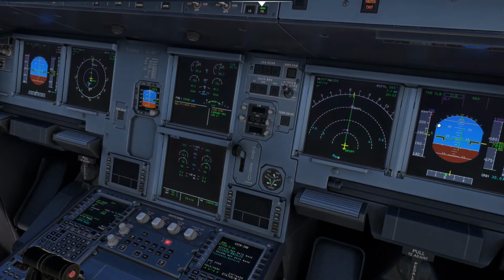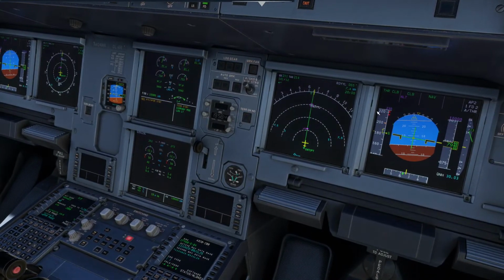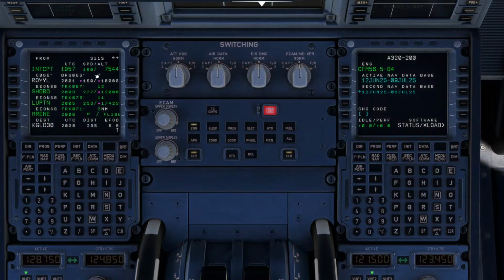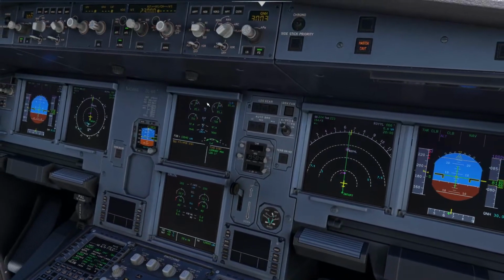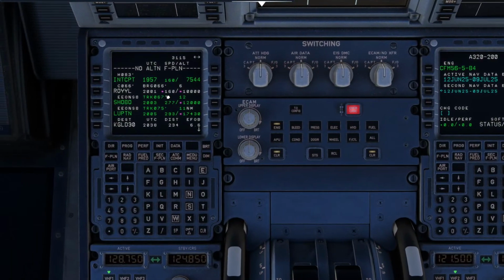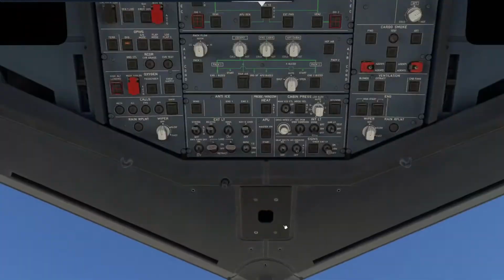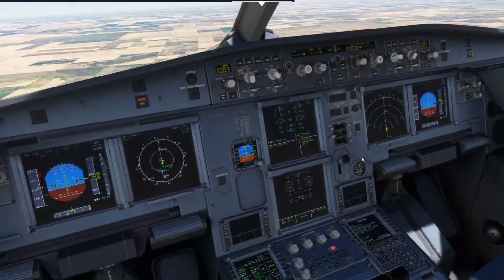And if you notice, look what airspeed it's going to go to. The 230 we have set in the FMC. Yep. So if I go back to the flight plan, 160, I had 230 set in here. Where'd it go? Oh, disappeared. Not sure why. All right, well, evidently for some reason it deleted my speed, and now it's just going to fly these managed speeds. Or, if I don't want to bust the 250 below 10,000, I can always, let's go ahead.